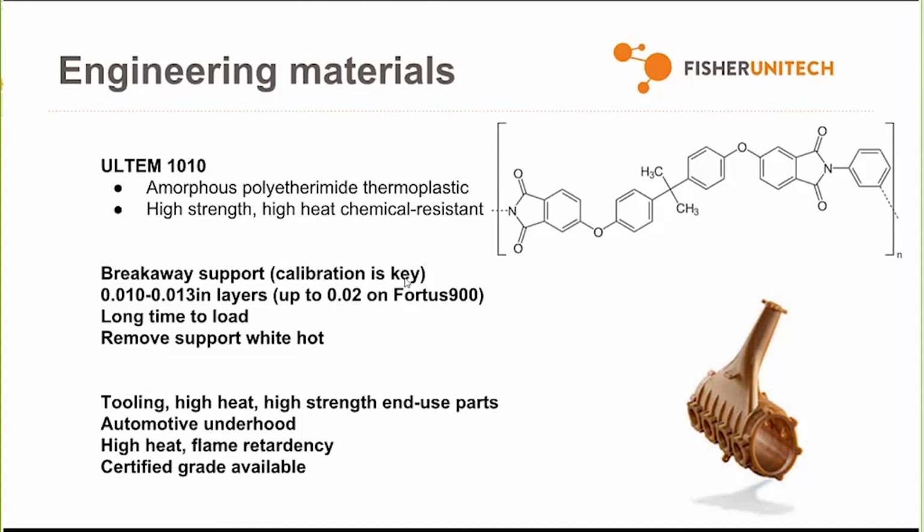Now, with Ultem, technically every time you heat cycle that, the bond between the model material and support material becomes stronger. You are essentially annealing that chemical bond. So you're going to want to act fast, because after, say, 6, or we'll call it half a dozen cycles through the oven, depending on the size of the part, it'll become very difficult to remove that support material.